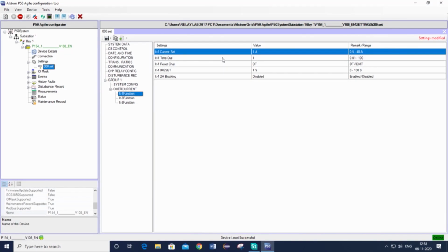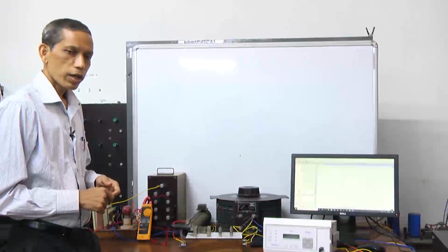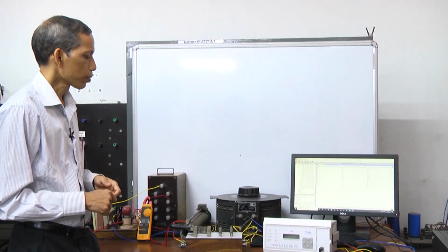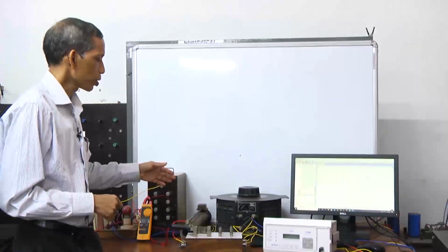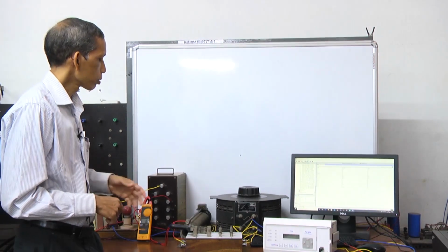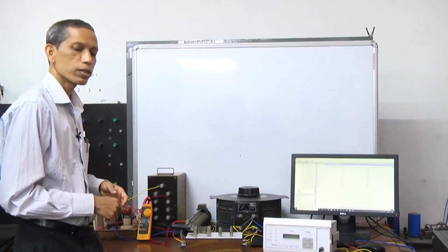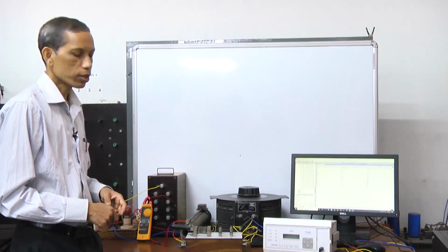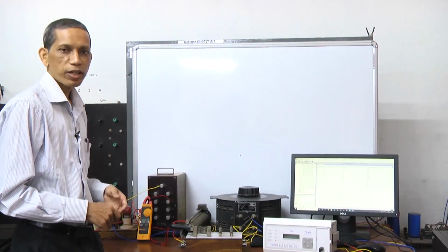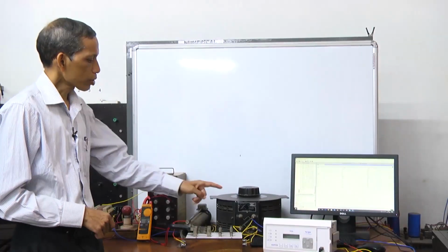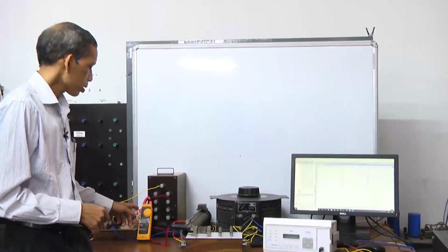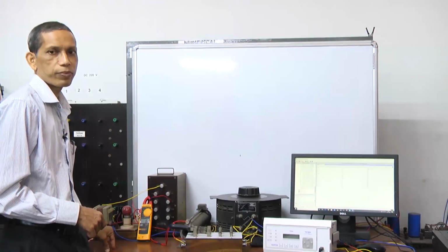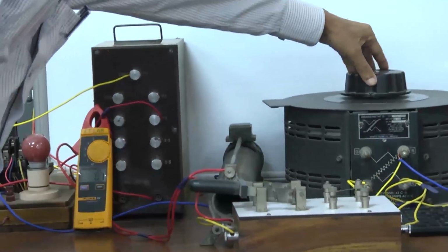We can also see, after the demonstration, how we can go for the recording perspective. So, now we will have the demonstration for this experiment. First we will see that once we inject current through this autotransformer into the power system circuit, the faulted path circuit, how the corresponding relay sees the current through the CT. So, that we will first verify. The relay current can be seen from this PC monitor, and the circuit current will be seen through this clamp meter. So, the circuit is already connected.